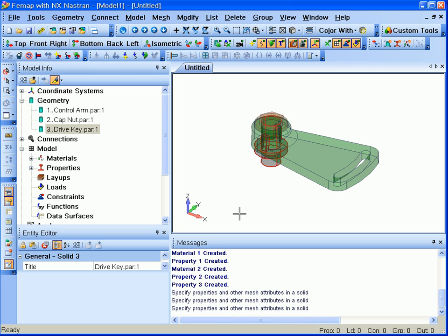Now, if you want, in the SolidEdge assembly model, you can pre-assign the material properties, but be very careful because the material data in SolidEdge, even though you may have it defined in megapascals, will always come over in pascals because it's metric. So you'll see that the modulus of elasticity is very high.